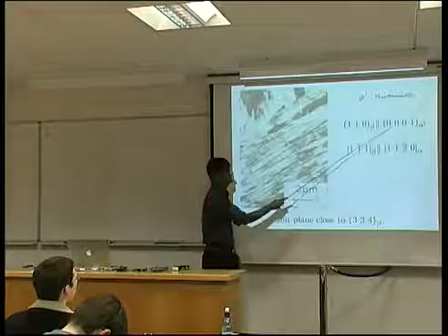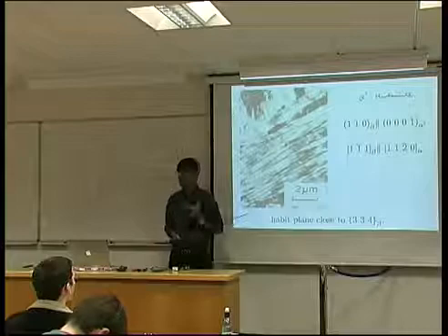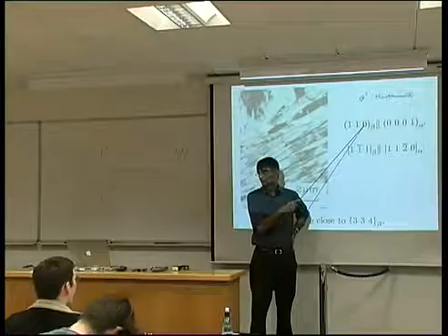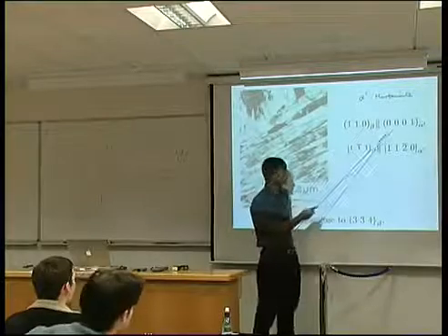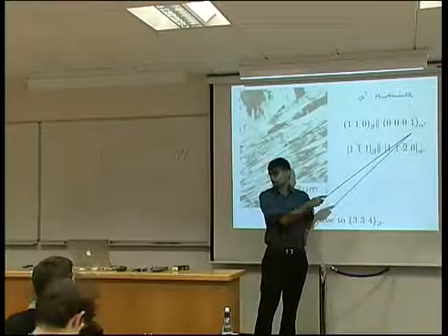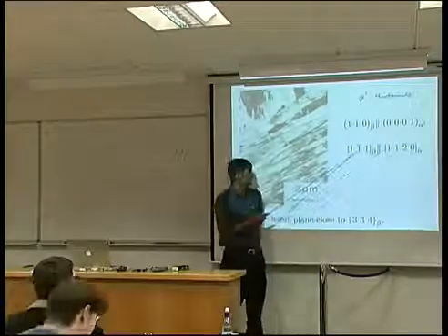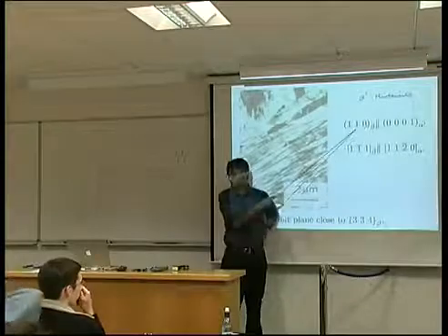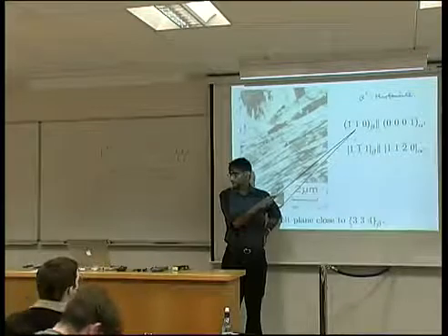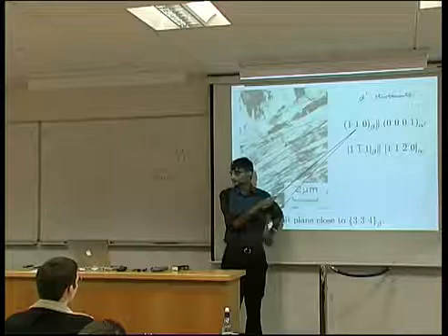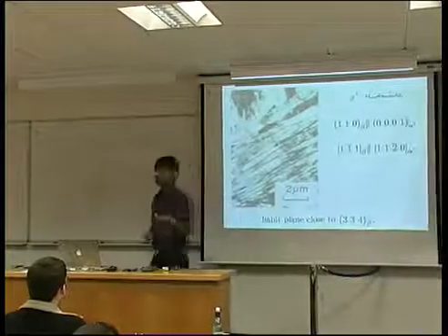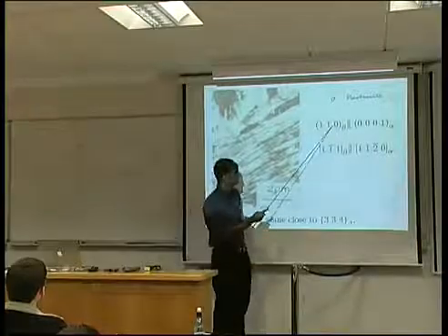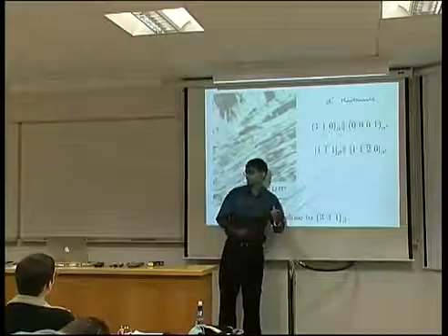And there's a particular orientation relationship between the parent and product phases. So you can see the close-packed plane of the body centered cubic structure and the close-packed plane of the hexagonal martensite. And this is the close-packed direction within that close-packed plane. This actually isn't completely close-packed. It's the closest packed plane you can find in a body centered cubic. A body centered cubic lattice has no close-packed planes, but this is the closest packed plane. This is the close-packed direction within that plane, and this is the close-packed direction within that plane.